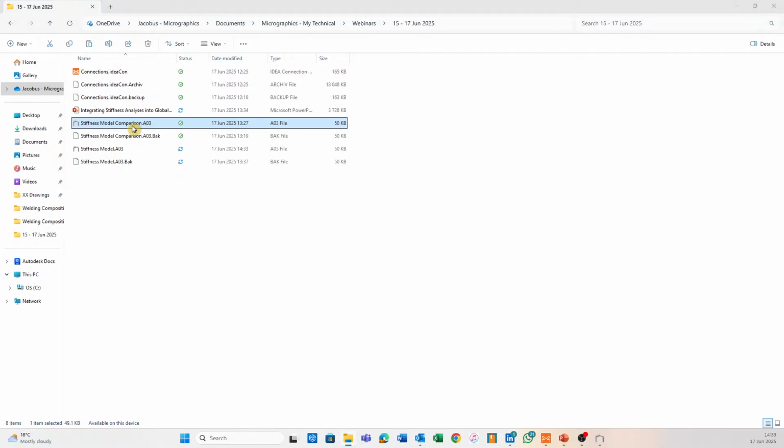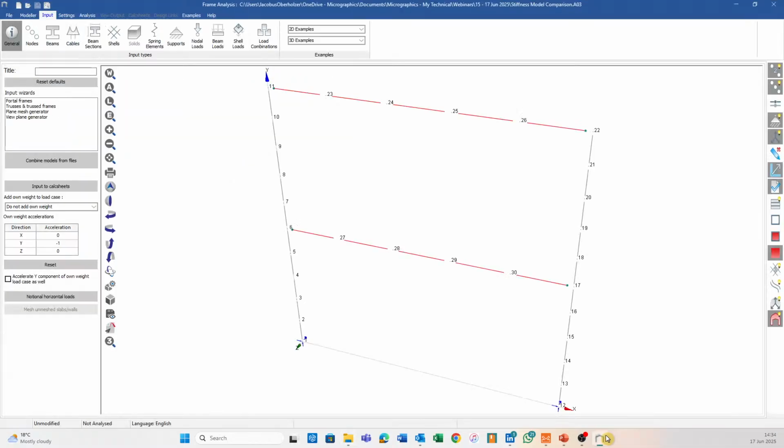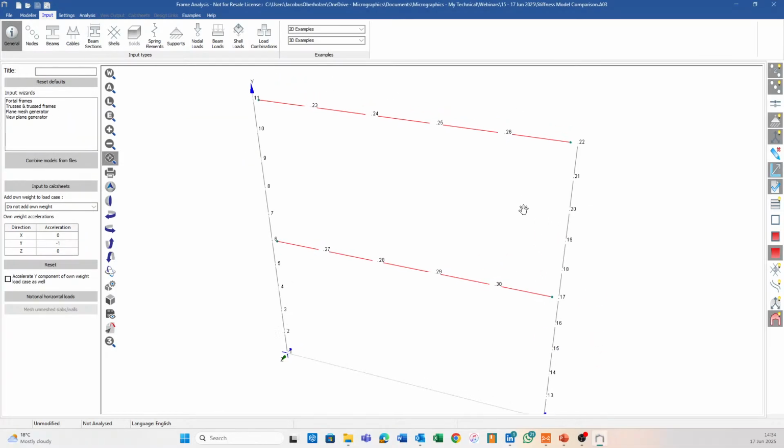So we're going to look at the output when we set the beam connection to the column as pinned, look at the deflection and bending moment, and we can do the same then for fixed as well. So we're going to look at those values. Then we're going to go back into our model with the springs, and we're going to see how we simulate pinned and fixed, and what is the actual rotational stiffness value for that.